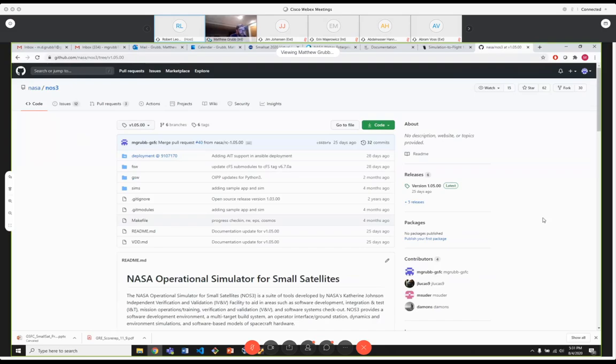It does. The maneuvers and the actual algorithms are going to be up to the developer, the flight software developer, the ACS software developer. So you have a reaction wheel included. It is generic, so you would want to change that model to be the actual reaction wheel that you're going to talk to. And you would also need to add whatever other components are used in your algorithm. If you have star trackers, magnet torquers, sun sensors, those things. All the functionality is there, but again, this is the open source NOS-Cube, kind of like your starting point. So we give you the examples to build up a full simulation.